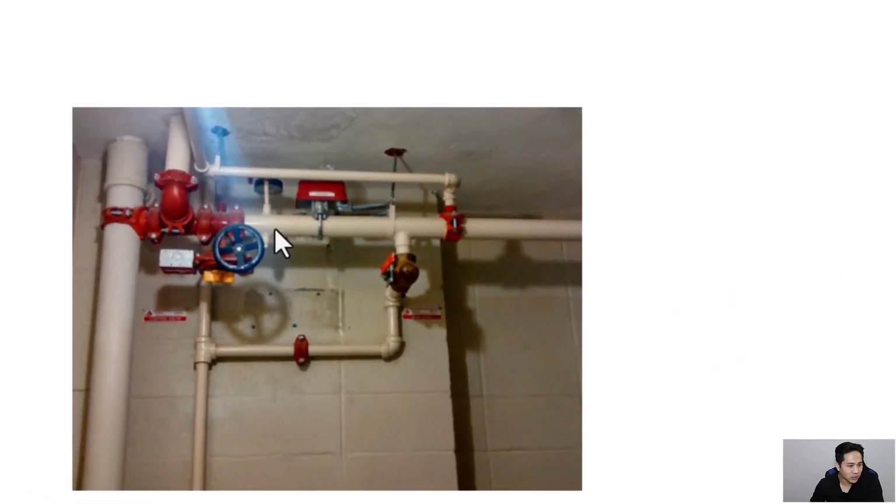And this is generally required in high-rise buildings. So, where the distance from the lowest level, basically street level, to the floor level of the highest floor is more than 75 feet is considered a high-rise. And in that case, you basically need floor control valve assemblies to be able to shut off the sprinkler system serving that floor if you want to do maintenance without affecting all the other floors.